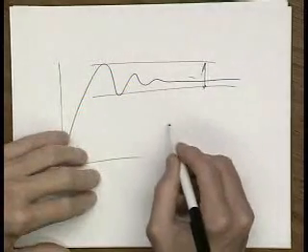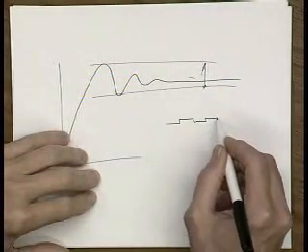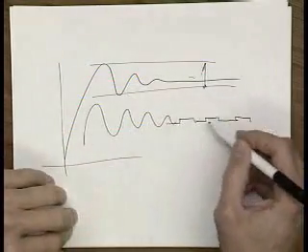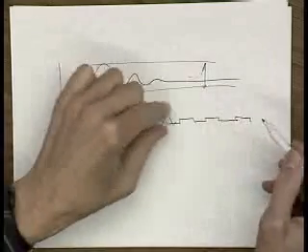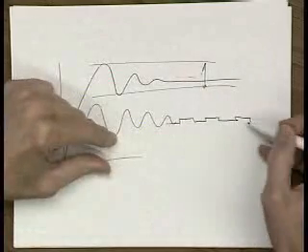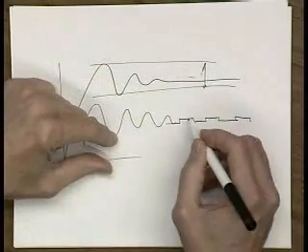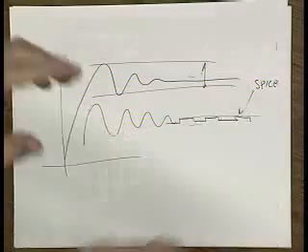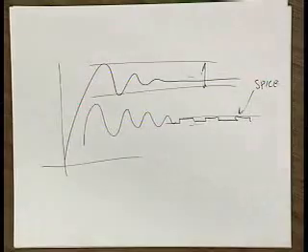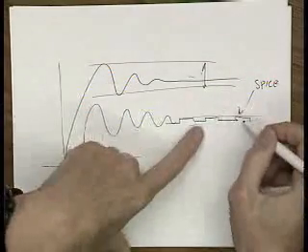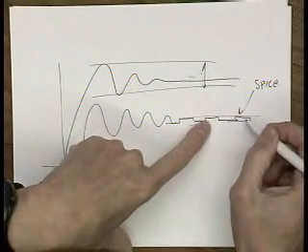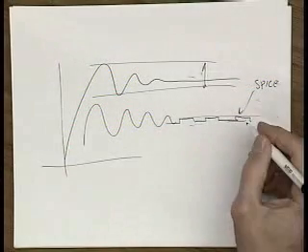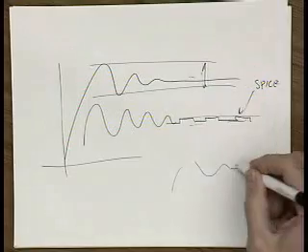Particularly if you see your answer start to oscillate like this, it can be ringing, and then when it finally gets really small, it can just keep jumping around a little bit. What this can be is due to SPICE. SPICE is an iterative solution, right? There's a spec you give it on how accurately you ask SPICE to calculate, and it keeps iterating.